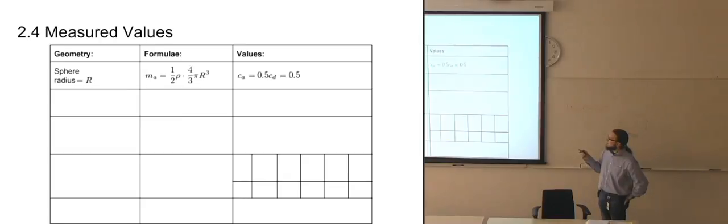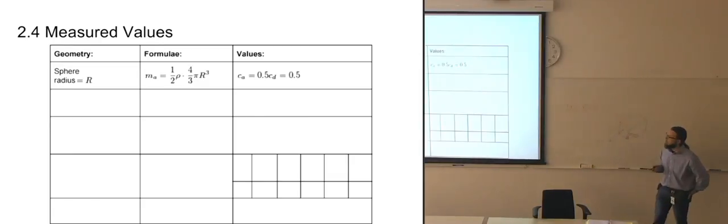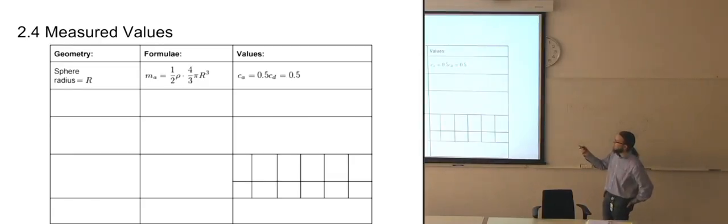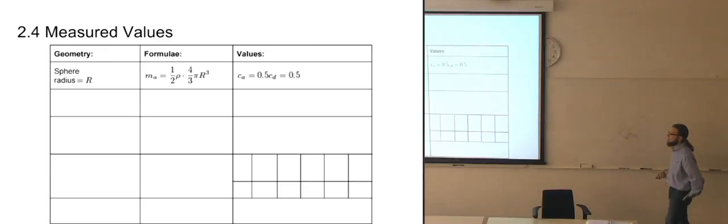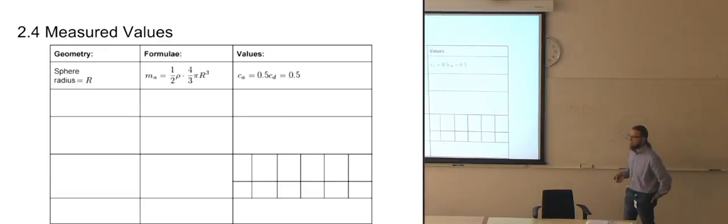And that usually means that we have an added mass coefficient, which is half of the drag coefficient, and the added mass coefficient is 0.5. So if you want to figure out the drag coefficient, you just solve this equation and then you get it. So the drag coefficient will be 1 in this case.